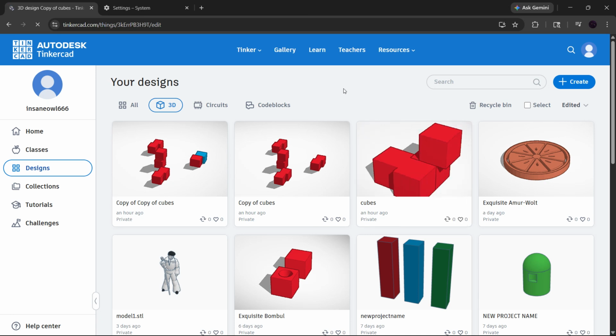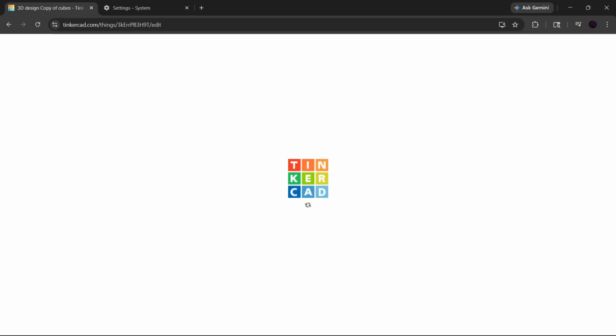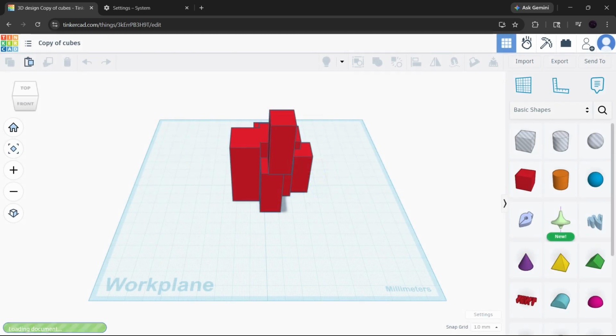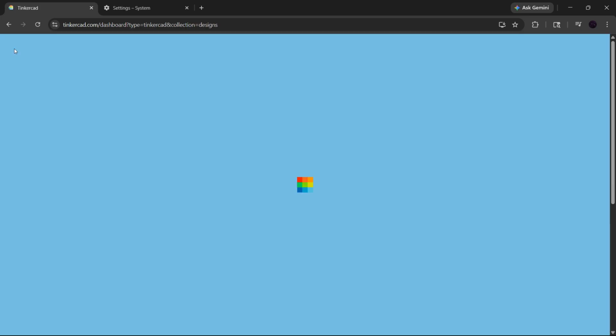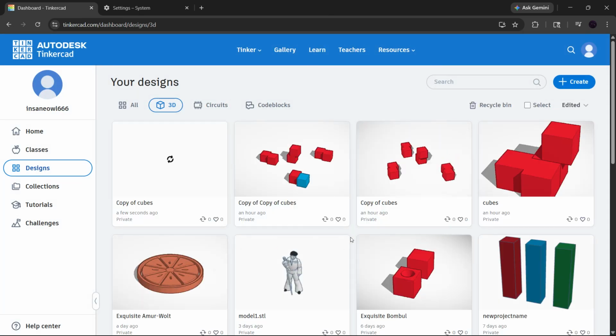So to recap, if you have a Tinkercad error with scaling an object, check for locked objects, zoom out for hidden handles, ungroup complex models, use Shift and Alt for better control, lower your snap grid, move the design closer to center, reduce heavy STL meshes, and turn on hardware acceleration if needed.